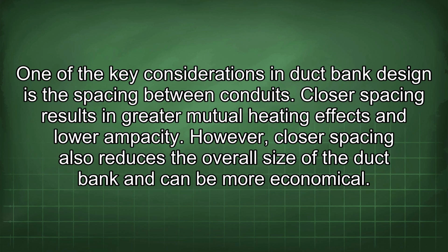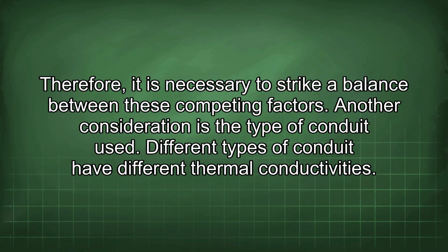One of the key considerations in duct bank design is the spacing between conduits. Closer spacing results in greater mutual heating effects and lower ampacity. However, closer spacing also reduces the overall size of the duct bank and can be more economical. Therefore, it is necessary to strike a balance between these competing factors.